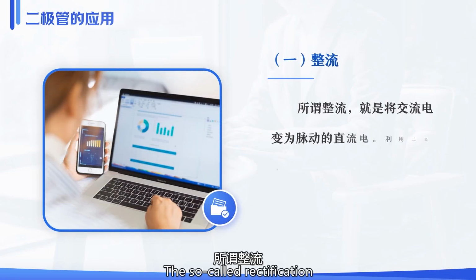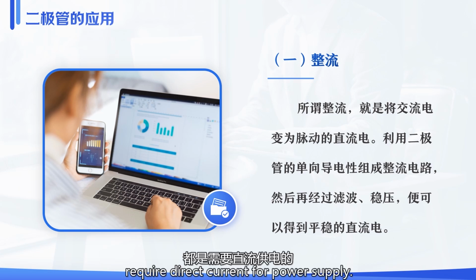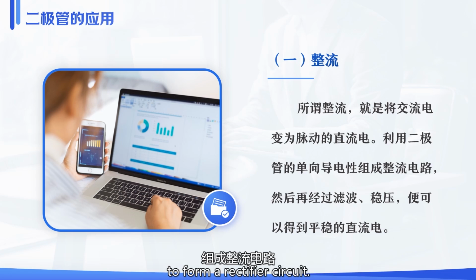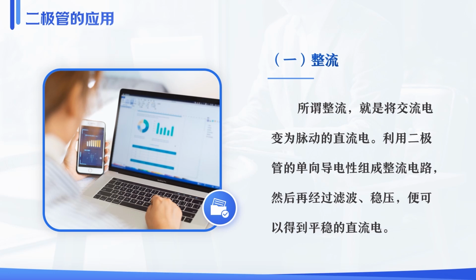Rectification. The so-called rectification is to convert alternating current into pulsating direct current. Many electronic products in our lives require direct current for power supply. Diodes are applied in rectifier circuits by utilizing their unidirectional conductivity to form a rectifier circuit. Then, after filtering and voltage stabilization, we can obtain stable direct current.